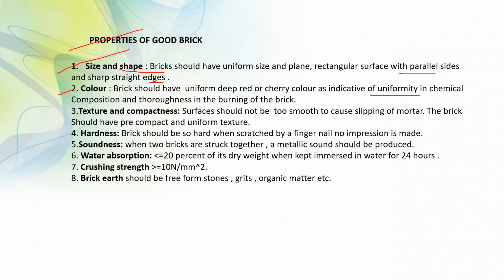in the burning of the brick. Next, texture and compactness. Surface should not be too smooth, to avoid slipping of mortar. The brick should have a compact and uniform texture. Next, hardness. Brick should be so hard that when scratched by a fingernail, no impression is made. Next, soundness.